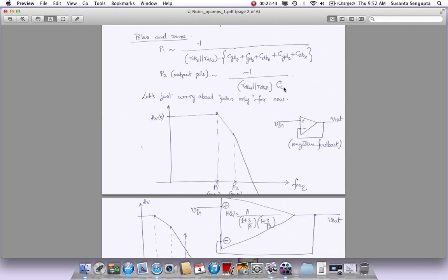It's not important which one is bigger at this point, because I'm trying to make a different point, which is that it could have an effect in systems like this. Wherever you have two poles, it could actually convert a negative feedback system into positive feedback. That is the biggest concern we have, and that's why we go to something called compensation. Let me try to explain what happens when you have two poles.